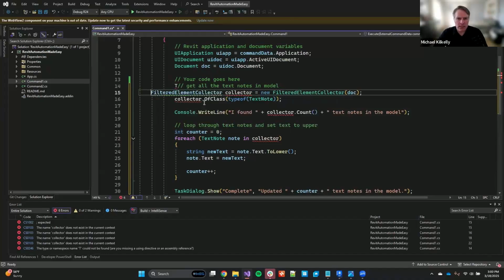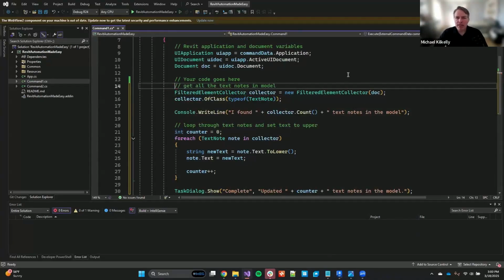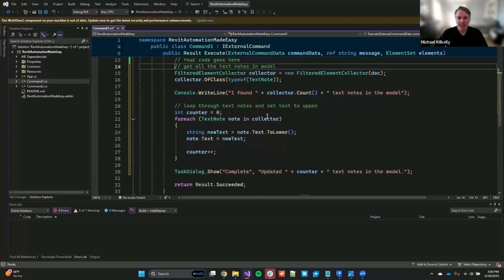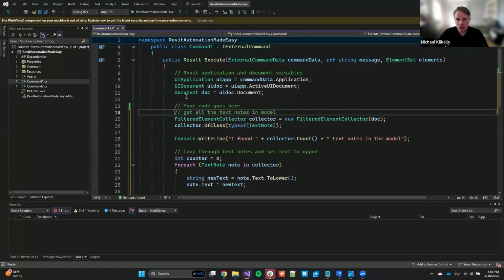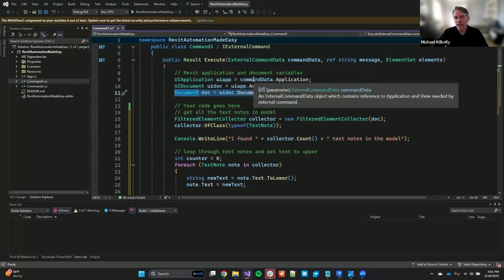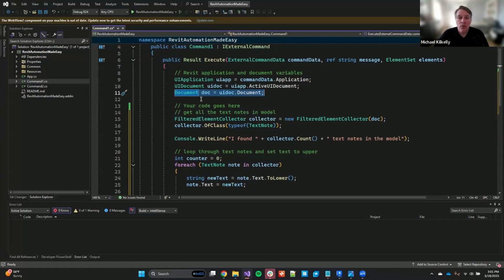And let's see, do a little bit of cleanup, but for the most part, this would be ready to go. I could build this code right here. I do have my document variable declared. Launchpad declares this document variable for me automatically in Visual Studio. I just need to make sure I have a variable called doc that relates to the current document inside of Revit. But that's really the essence.